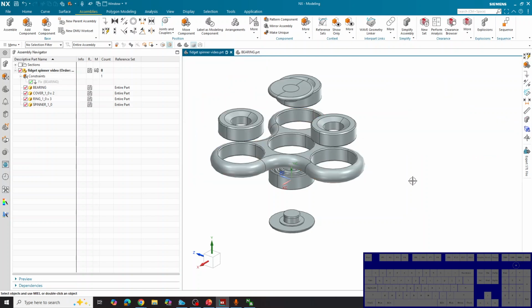By the end of constraining and making your final assembled fidget spinner, you have reduced the degrees of freedom of most of your components. It won't always be 0, but some of your components might end up being 0. For example, the bearing over here can't move at all, it can't rotate either, so that has 0 degrees of freedom. Okay,